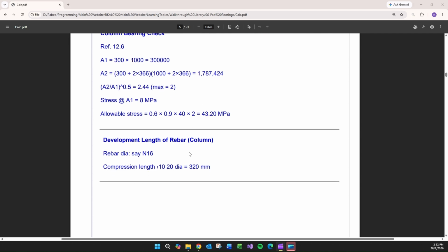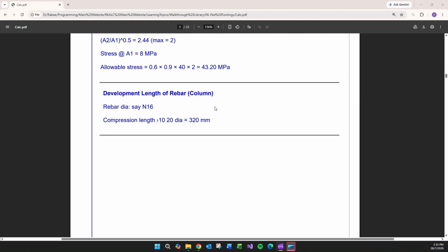And development of the reinforcement. This is a compression case, so the development will be circa 20, 25 diameters. Shouldn't be any problem there, especially that the column here doesn't require more than 16. Even if your columns are at 24 or 28, which might be dictated by buckling, but the section capacity itself would work there in 16. So that is a matter of judgment.